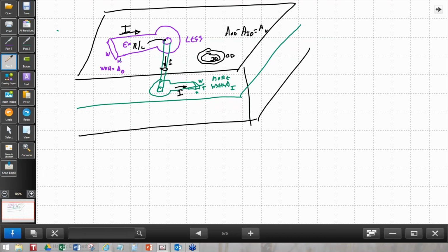As a general rule, if this is adequate on the outside, and this is adequate on the inside, but this is the larger of the two because it's on the inside and cannot dissipate heat, I would say you need to make the cross-sectional area of the via roughly equal to the size of the trace on the inside, because that's the worst of the two. There will be some heat able to get away from the via. It can conduct up to the surface and onto that trace, and it can conduct down and onto the other internal trace. But its ability to dissipate is somewhat limited.